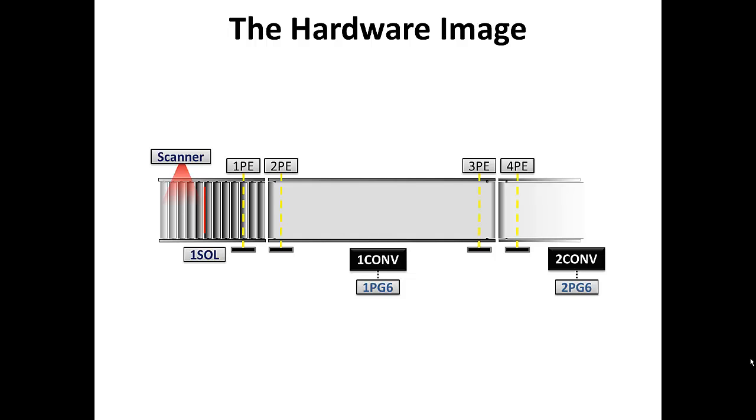When the middle conveyor, the buffer conveyor, turns on, it's going to pull the carton through the photo eye, 2 PE, and the idea is to pull it onto the middle conveyor until it just clears 2 PE and then stop. So if we do that continually, we should be able to get 4 cartons or containers onto this middle conveyor section before it's full.